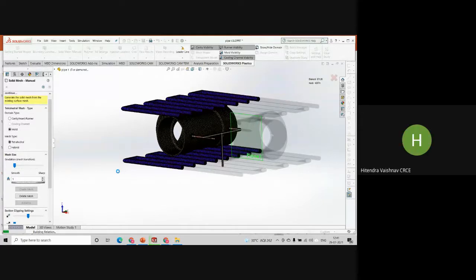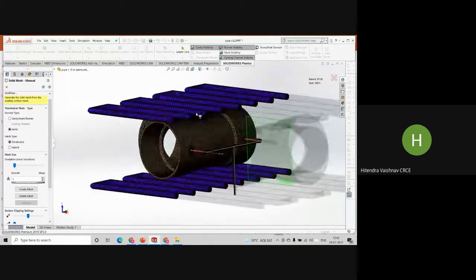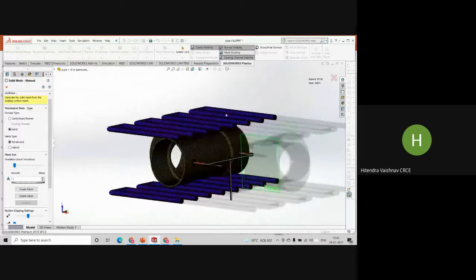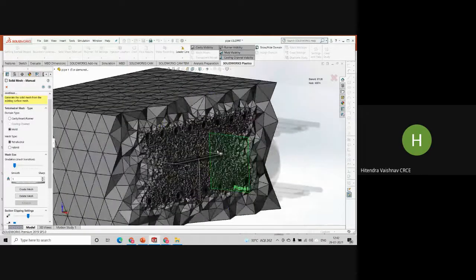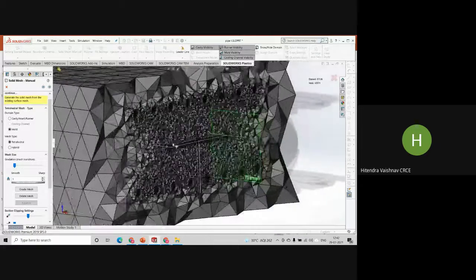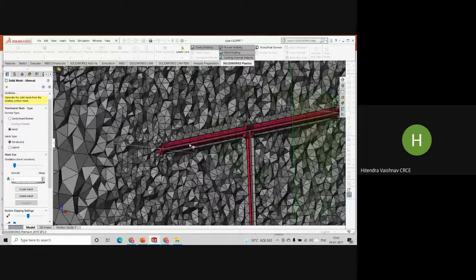Advait, there is one more thing when you talk about the hexahedral mesh, or when it is used more than the tetrahedron. Whenever we go for a finite volume analysis, that mesh is very important. Now look at your example. The cooling channel has a fluid inside, right? That is the reason it automatically takes the hexahedral mesh. Same with the runner. In the runner also it is plastic which is flowing through. So that's why it takes hexahedral.